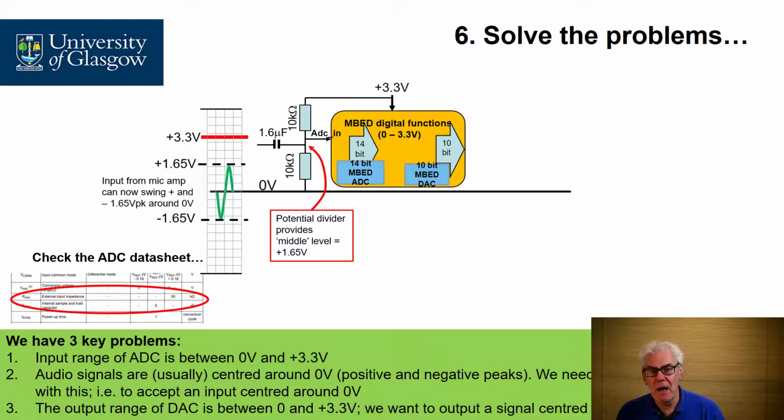We've also included a capacitor here, and that capacitor allows us to connect or remove the DC component and allow us to connect a signal that is symmetrical around 0. It's important to realize that you need to calculate out the value of that capacitor because that will reject some of the low frequency information, so you need to make sure it passes all the audio information.